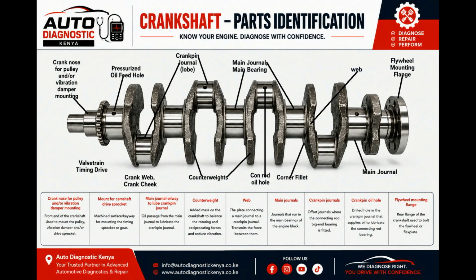Nose of the crankshaft and timing drive. At the front of the engine is the nose of the crankshaft, and this end drives several components. One of the most important is the camshaft. The camshaft controls the opening and closing of the inlet and exhaust valves. In most engines, the camshaft is driven from the front of the crankshaft. The crankshaft extends beyond the front main journal, and that extension may be constant in diameter or stepped. Mounted on this area is the timing drive.